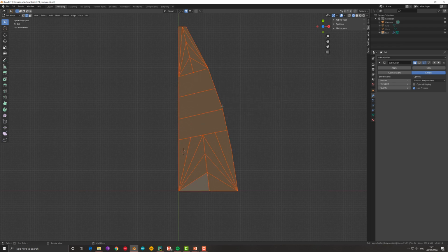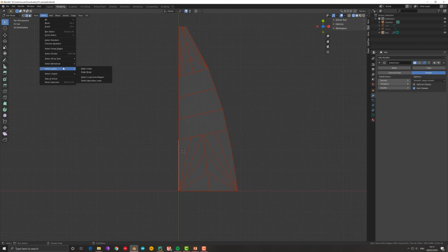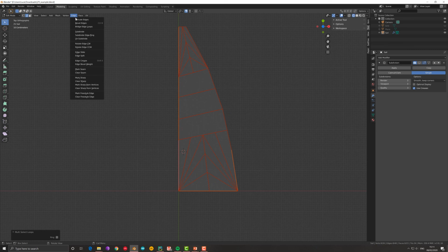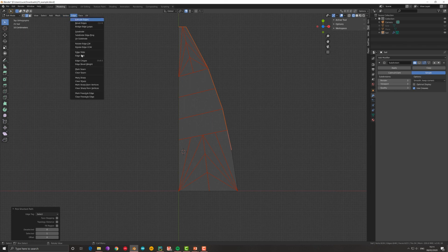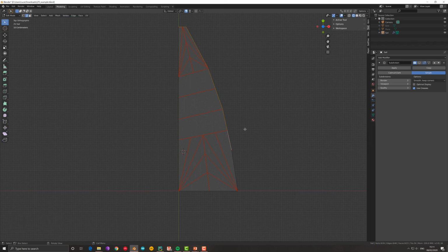Everything is a seam. Let's remove the seam from the peripheral, which is not necessary, but just to show how to do it. I click on one of the edges. I go to select edge loop, and part of it is selected. Then I go to the edges menu and I say clear seam. Then I go to the first edges, pressing Ctrl to add other edges, so my selection follows, and again I go to the edge menu and I say clear seam. Okay, now only the internal edges are seams, which is elegant but not necessary.